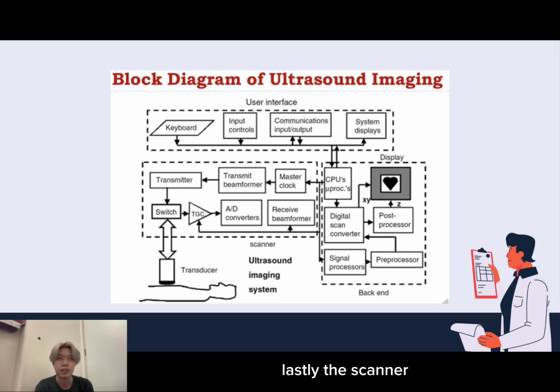Lastly, the scanner. It includes the master clock, which is a central timing reference for the entire ultrasound system, and synchronizes the timing of all the components, ensuring that the ultrasound pulses are transmitted in a coordinated manner. The transmit beamformer helps to generate and shape the ultrasound pulses. It controls the timing and amplitude of the electrical signals sent to the transducer elements, hence producing a focused and